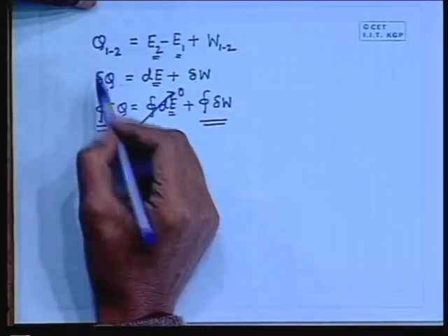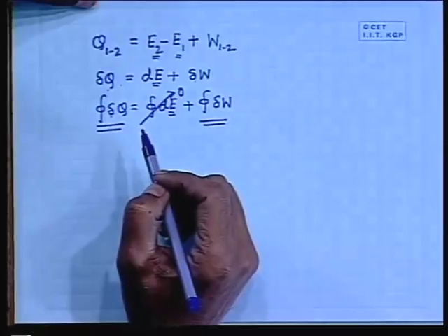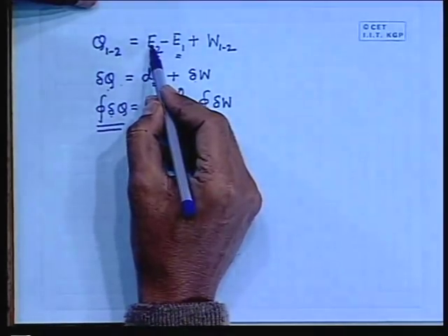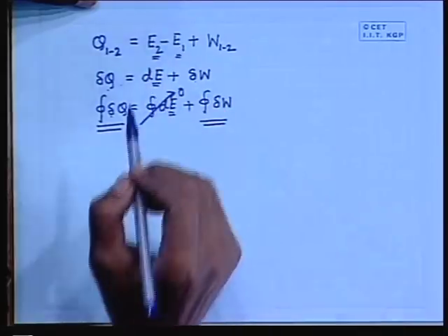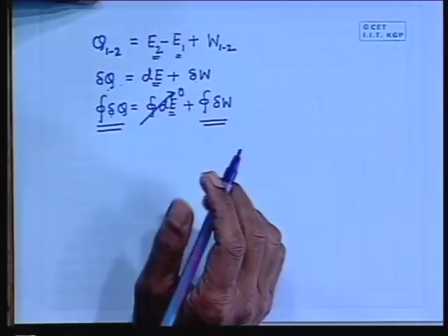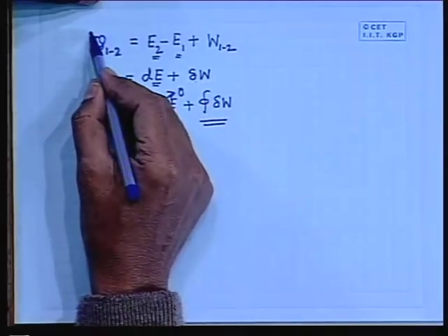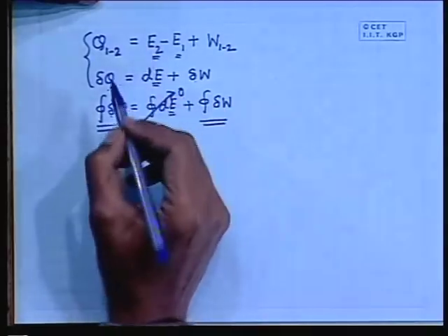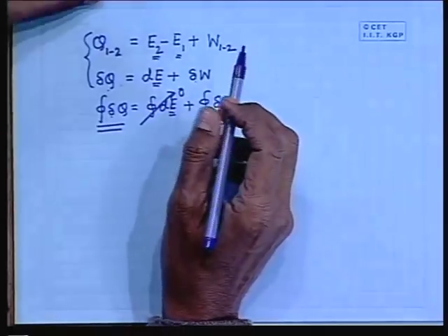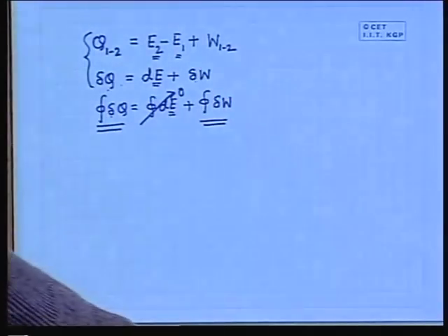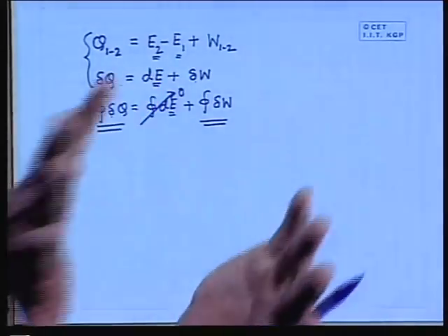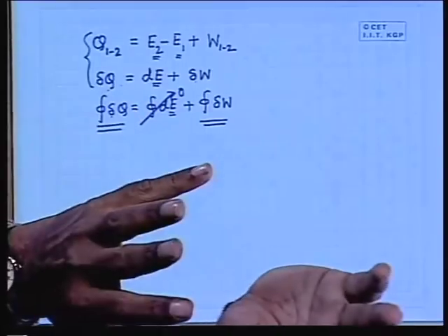Now if we write this in terms of per unit mass, this will be internal energy per unit mass. But before that I should tell this way. Now you concentrate on these two equations. First of all you must know this first law, that heat added is change in internal energy plus work done, is applied for both closed system and open system.